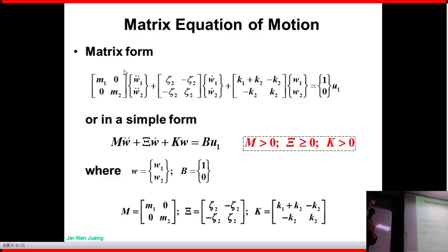Well, the answer is no. But if you know the dominant frequencies, if you look at it in the modal coordinates, then M1 and K1 can represent your frequencies very well. So don't just say, well, this is too simple, only one mass, one spring. That doesn't look like the 101.